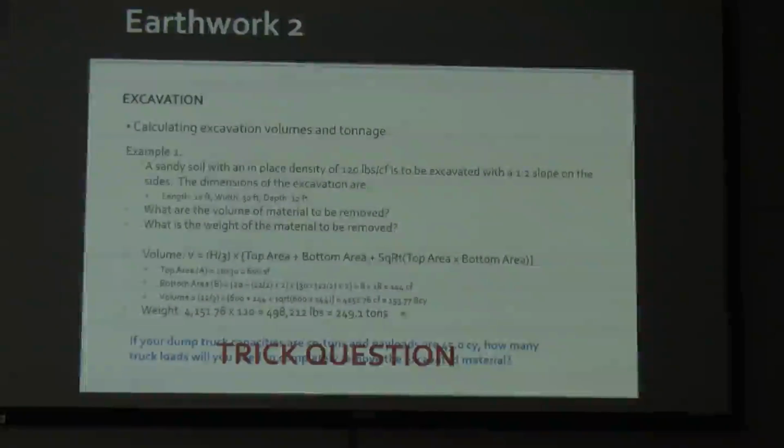Our weight isn't affected, but the material that we remove, because air fills in a lot of these spaces in between the solid particles, our density goes way down, and therefore our volume of material goes up when we remove it from its in situ condition. So the loose cubic yards of the material removed can be much greater than the bank cubic yards, or the volume of the material as it's in place or in situ.